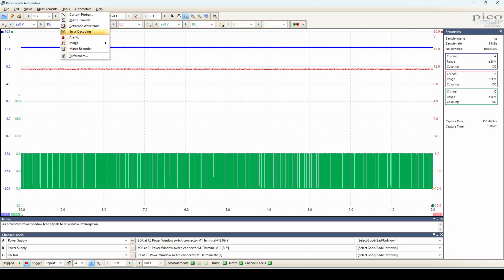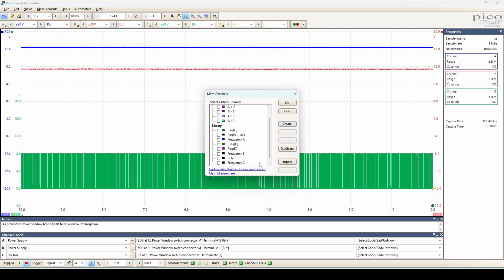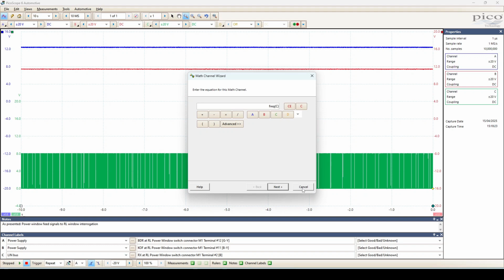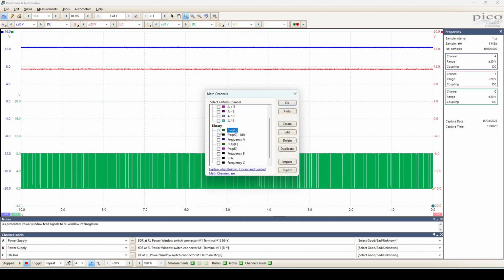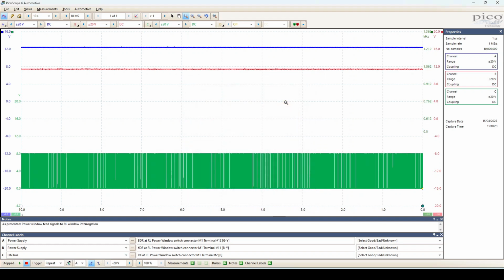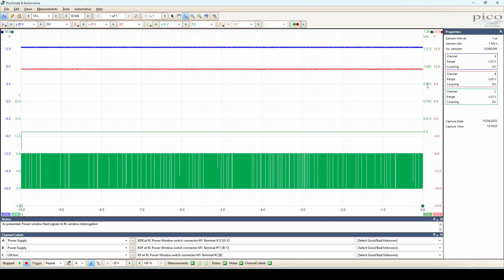Let's take our math channel. And we're going to plot the frequency of C, which is here. Okay, let's cancel that. There. And then you wait for the frequency to come up. Now that is too high. My scales are not set correctly.